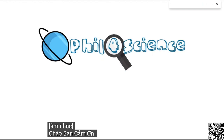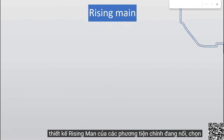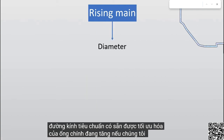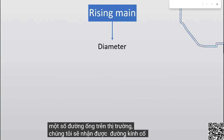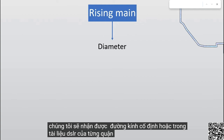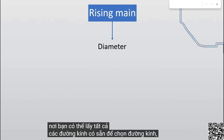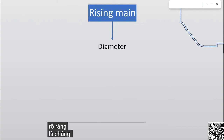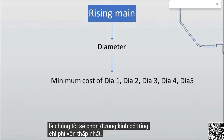So, design of rising main means selecting the optimized available standard diameter of the rising main pipe. If we survey the market, we will get fixed diameter pipes, or in the DSR document of each district you can get all available diameters. To select the diameter, we will use a cost criterion, as it is obvious. Means we will select the diameter which has the lowest total capitalized cost.